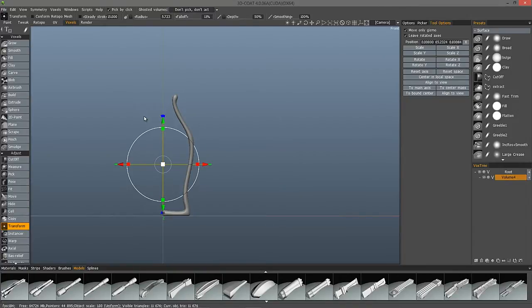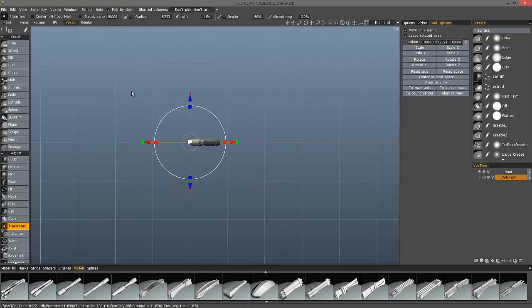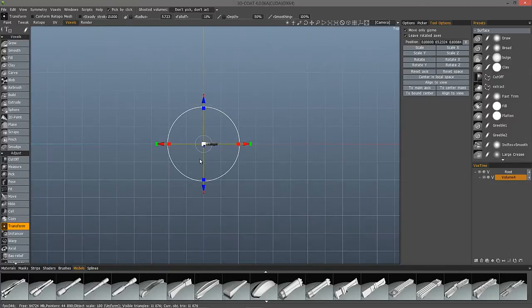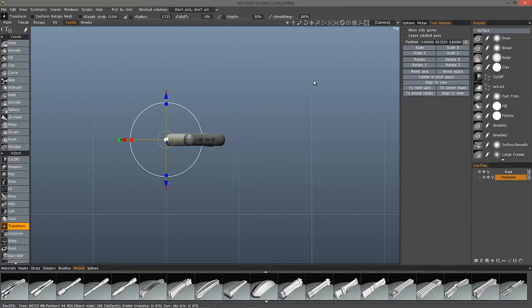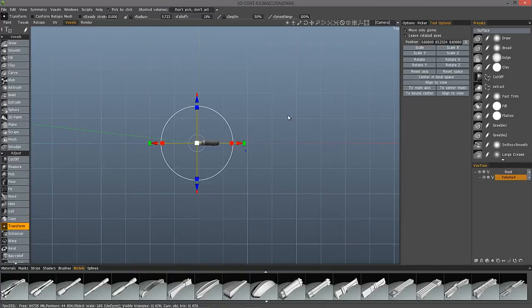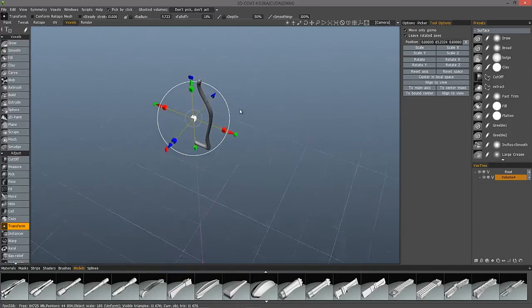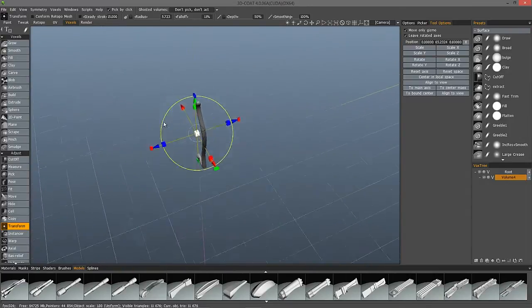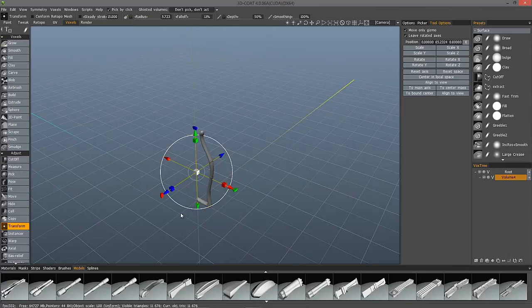And let's go to a top view. I'm going to hit the 7 key on my number pad, or you could go here as well. It looks like it's lined up fairly well right on the origin, so I don't really have to move this object. So now I'm going to click my little cube icon here, or the 5 key on your number pad to come out of orthographic view. So you can see again I'm right down the center of the grid at the origin.